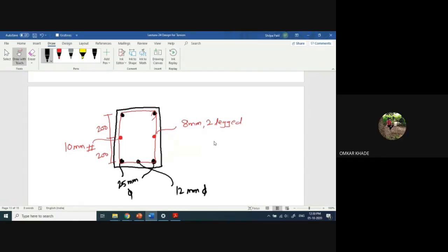And then this doesn't matter in the over reinforcement. Means it doesn't make the section over reinforced. No. Over reinforcement, under reinforcement, we decide based on the area of steel provided in the tension zone. Okay, we do not consider the steel provided in the compression zone, which is for minimum requirement. That we don't consider in the calculation of Ast. Is it clear? Yes, ma'am.